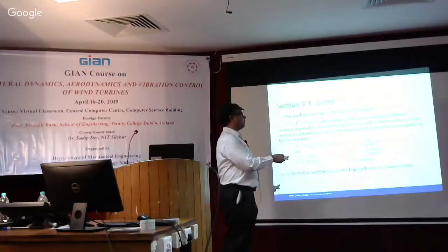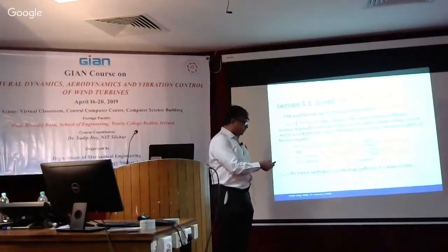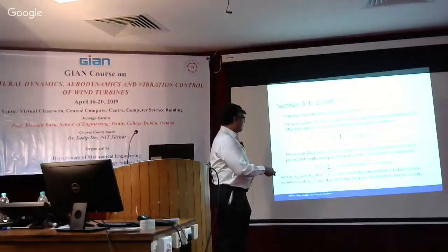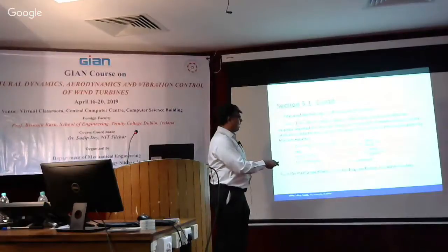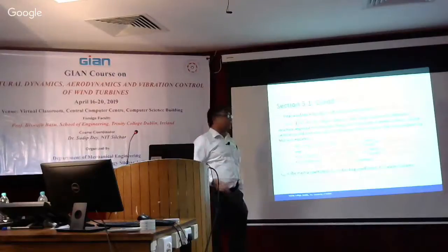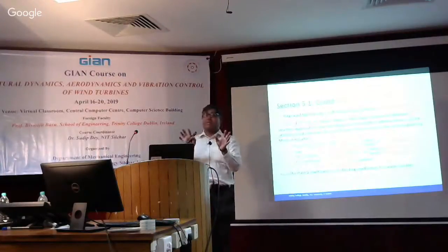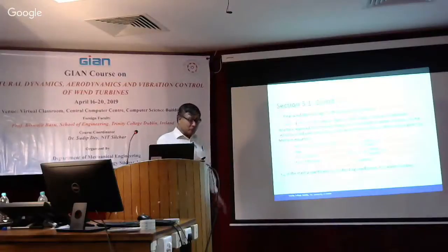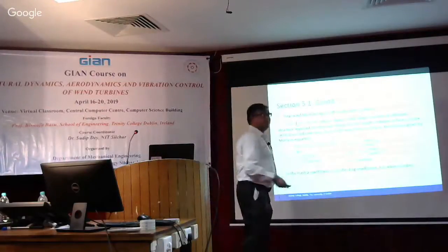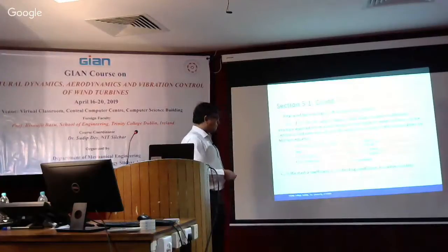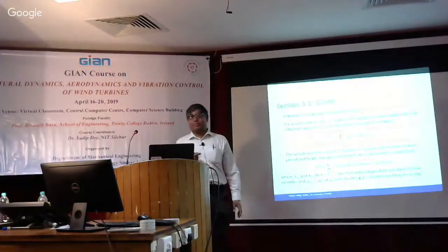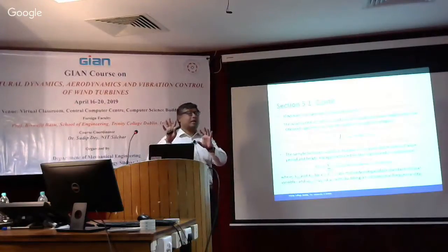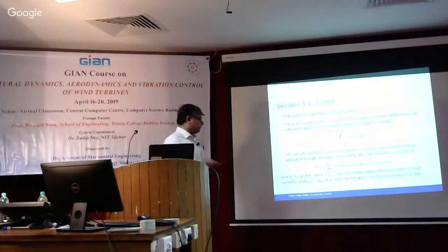So the spectra is giving you the function of time, which is the time series which we have now generated. So this is the x t. X t is essentially your eta t, and the space variation is given by this. So really what you can see here, the way this has been solved, is we have actually decoupled space and time. It's the product of the space and the time. And in partial differential equations, it's called separation of variables. So we separate the space and time and get the solution as a product of the two.